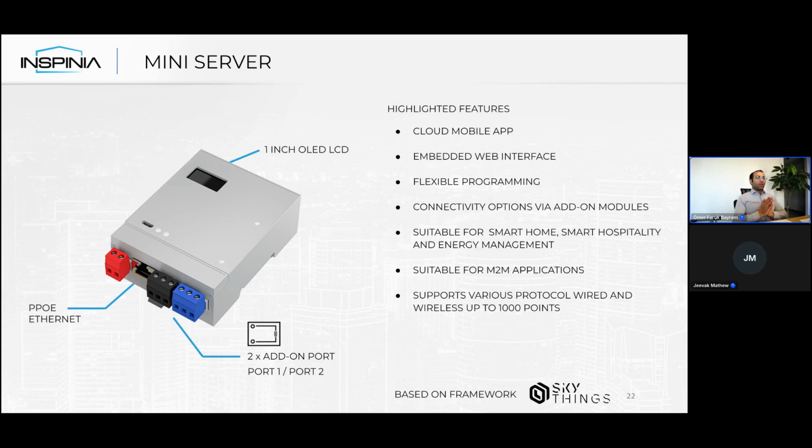In that case, you will already understand. For example, we have touch panels in one villa project. We put one touch panel at the entrance of the building, and we have many rooms, and every room has one 4-inch device. Do we need to give an add-on for every 4-inch or 8-inch and 10-inch device? No. We will just give the add-on to the main master device. We can select any of them as master device. Bigger size touch panels have 2 ports. That's why that will be more logical.